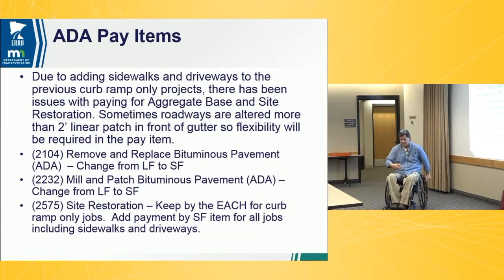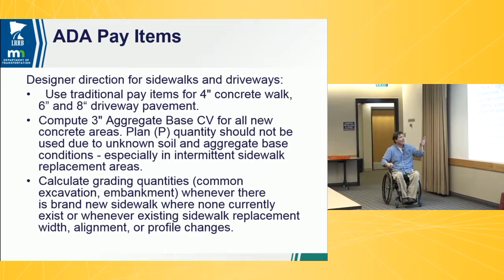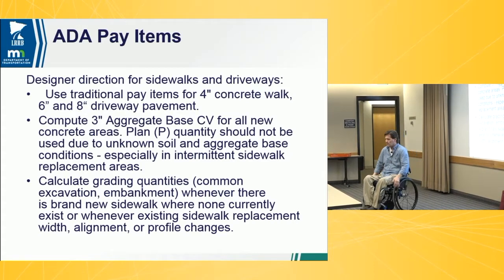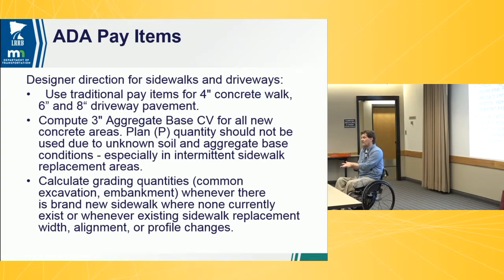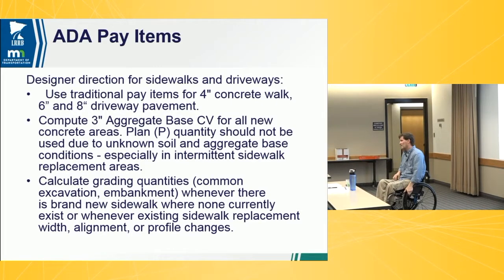So there are some pay item changes, and we talked about that. We are using traditional pay items underneath the sidewalk. But if you're just removing and replacing the walk, like a 5 foot walk, taking it out and putting back 5 foot, I wouldn't do any grading, obviously. If you're widening the walk, you might want to pay for that widening, or if you're changing the location or putting in a new alignment, just pay normally. Also, if you are lowering the profile, you should pay them for the cut, or if you're filling in. Just be fair, but don't knock yourself out, because these quantities are small. We just want to make sure we're being fair to contractors.